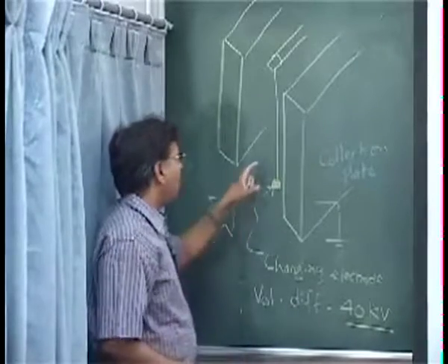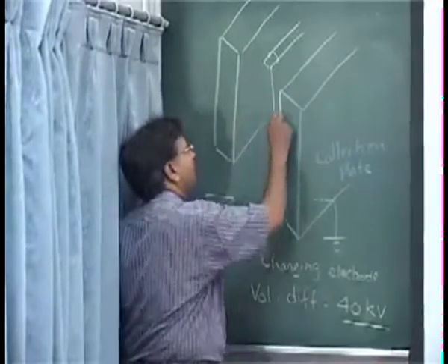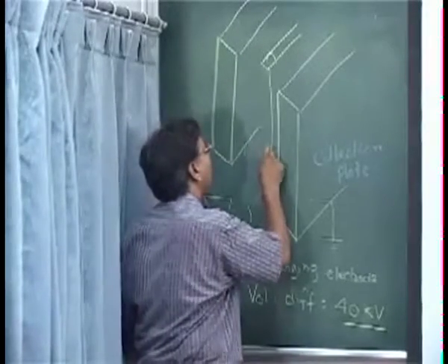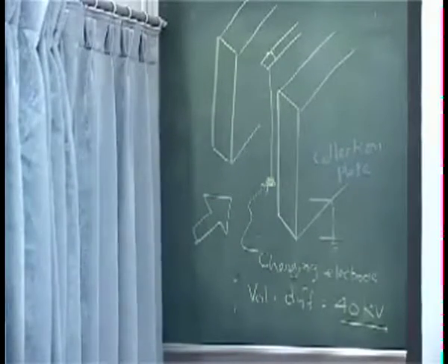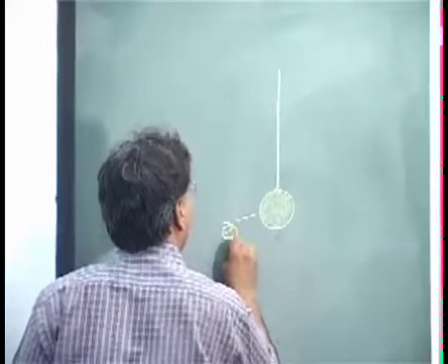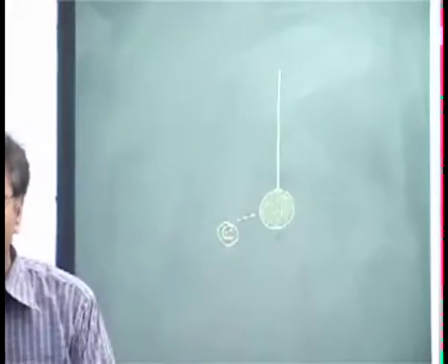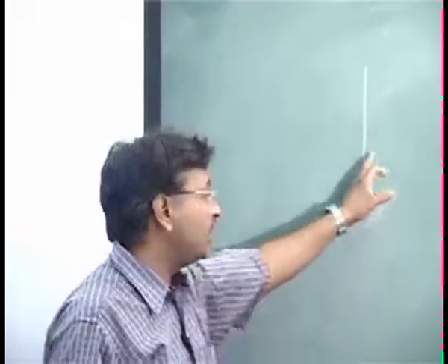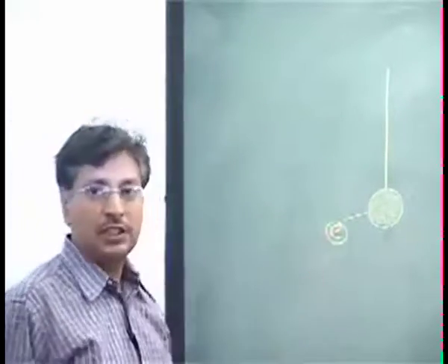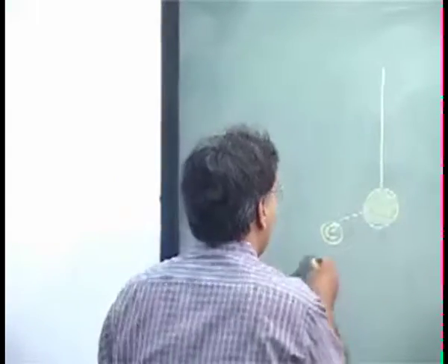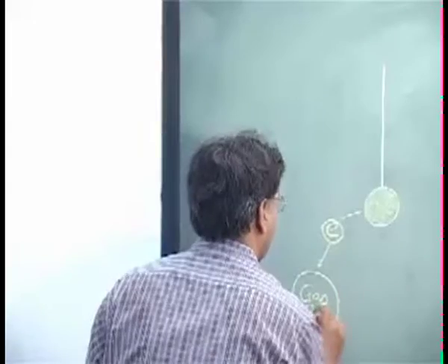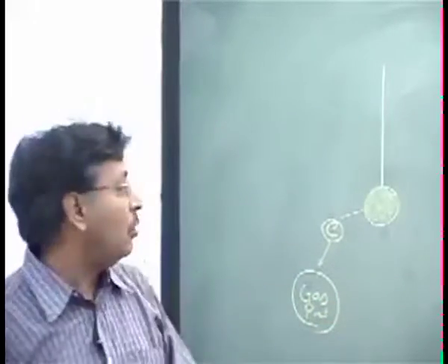Now this space is filled by the dirty gas with the particles and everything. There may be some electrons, as I was trying to show you yesterday. There will be some stray electrons in the gas stream; we always find some electrons in there. These stray electrons, once they see the negative charge, will be accelerated away from the electrode. They want to run away because they have the same charge. In the process, this acceleration is so much that they hit the gas particles. And remember, this is happening very, very close to the electrode; we are only showing it in a bigger picture.